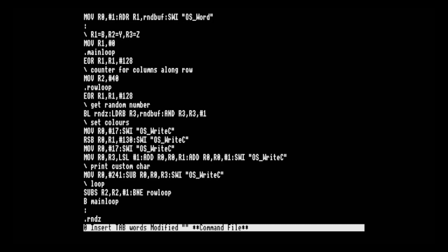Moving down a couple of lines, we've got this sort of complicated move with a shift left to do the multiply by 2, and then we're adding on R1 and then adding one more. Can we combine this at all into any fewer instructions? Well, we can do, because we can use the barrel shifter with the add instruction as well. It's just that the only thing we can use the barrel shifter for is the final operand in the add.